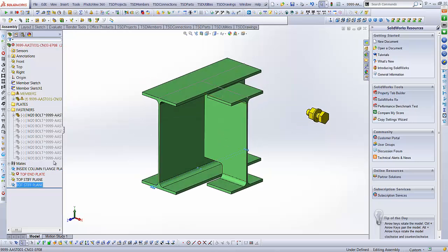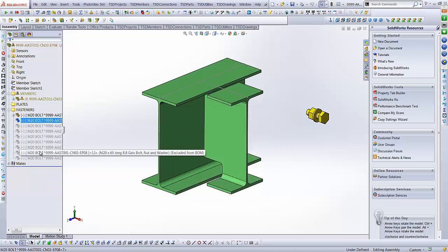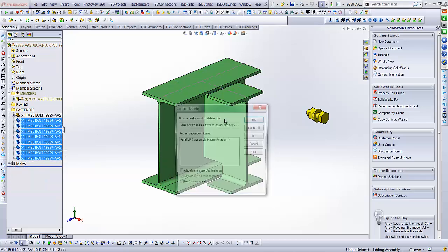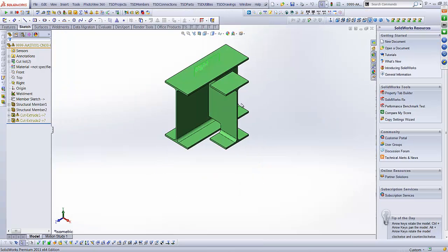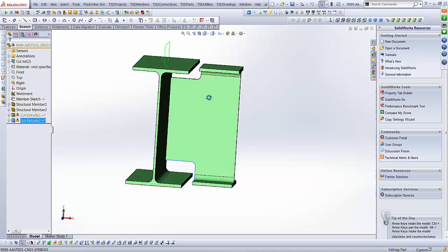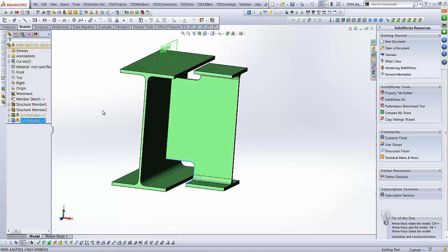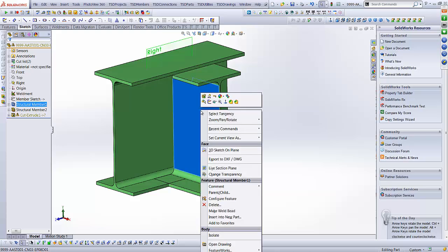Now there are other planes here that I'm just going to clean out. I'm just peeling it right back. There are some bolts here that have been suppressed due to configuration changes. Alright, so now I'm just simply left with this connection. Now I've got a trimming profile here, and also an underside one. I'm simply just going to remove the underside one because our PFCs are going to be smaller than our beams in most cases. This is a typical scenario.